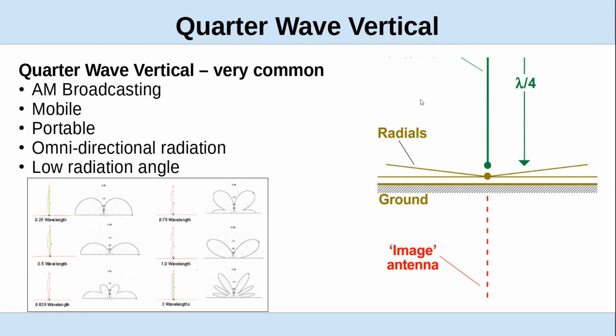There's some good studies on counterpoises versus radials. And usually with a counterpoise, you can get better efficiency than a ground radial system if it's a few wires that you're working with. Because in essence, if you look at it like in this picture, it's a vertical half-wave dipole, but one of the elements is this imaginary element in the ground.